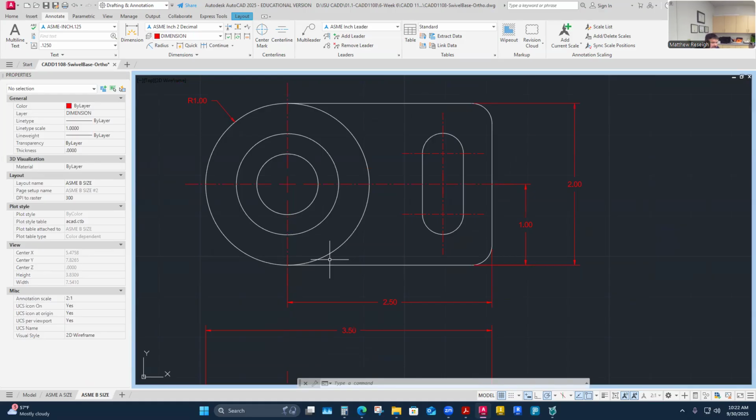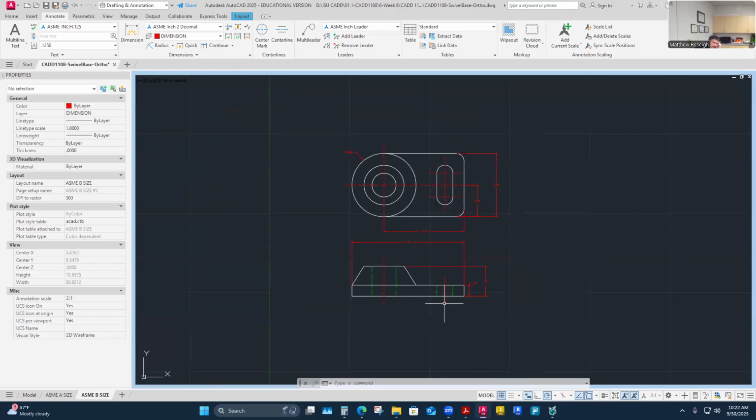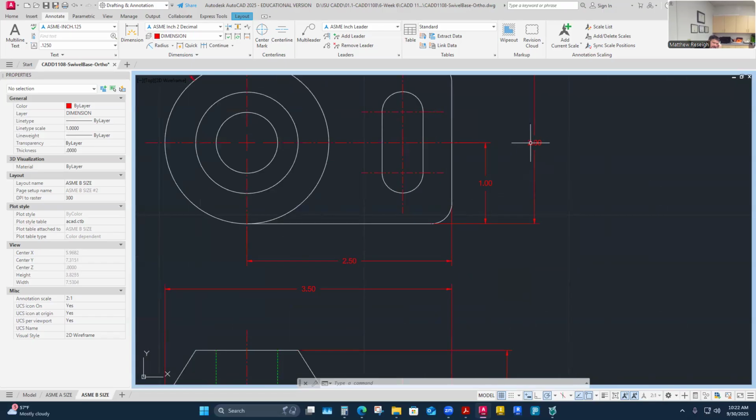So to me, this is kind of like location of plate. I've sized it and then I've even located it in kind of model space. So it's located off of a nice center line situation for the most part. Really, I'm doing its locations as these two. The 1 inch and the 2 1/4 are kind of locating that plate in from this center line here. I'm even viewing this one that I might consider pulling it from center out rather than from the front face, but it's really the first dimensions I've pulled.